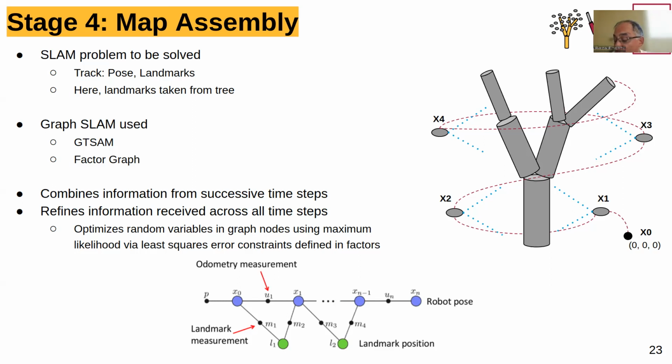The other question I have is mainly related to, I saw you're using a 3D LiDAR, and still I don't understand why you suggested moving in a pattern around the trees. Do you think that just collecting at one side is enough data? If you just move from one side of the tree, does it give you enough data rather than trying to move around the tree? Because for agricultural applications, it's really not practical to move around the trees because trees are in rows and usually the canopies touch, so you can't actually fly around them.